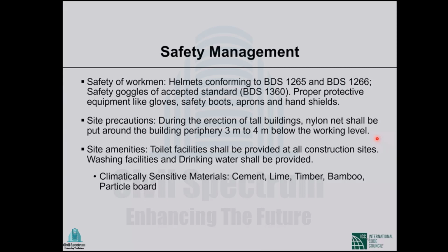A person died because of a falling brick on the head. So there are restrictions in the code. For tall buildings, during construction, you have to put a nylon net all around the periphery so that nothing falls from the top.